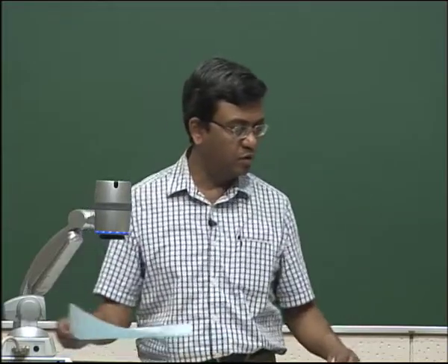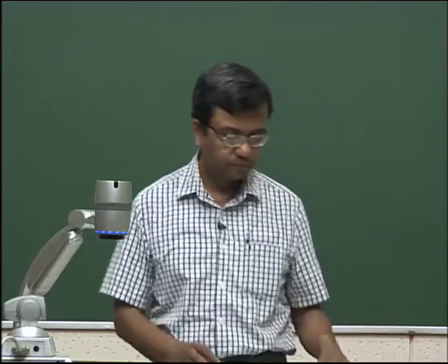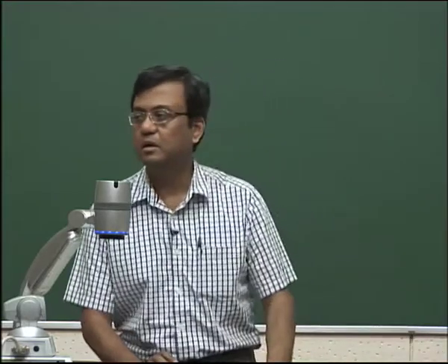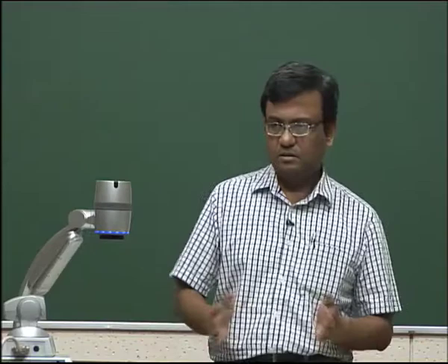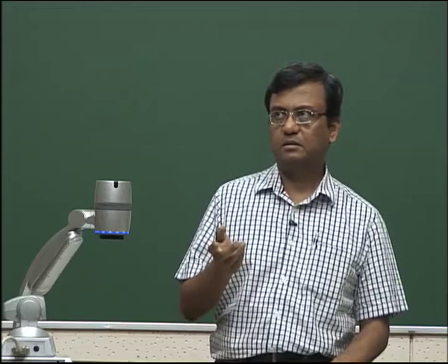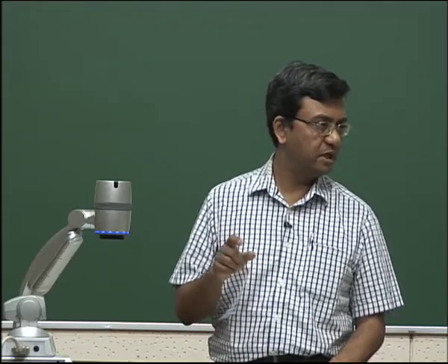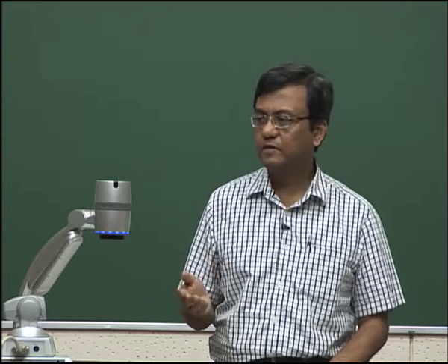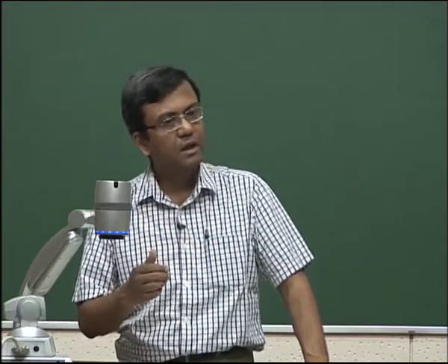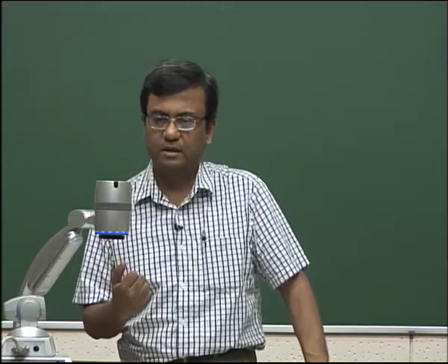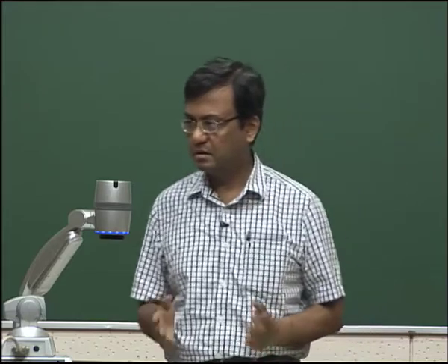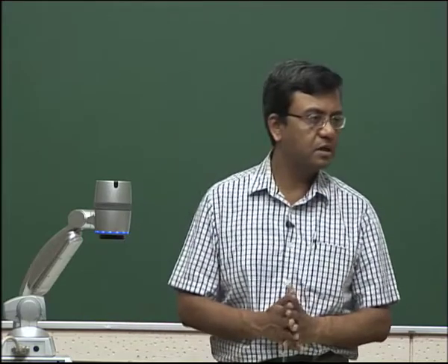So this is what we wanted to do with regard to droplet evaporation. Droplet evaporation is an easier problem which we wanted to work on. We saw that the equations are pretty simple. The only thing we needed was the mass conservation equation, to show that m dot is equal to constant, and also the Shvab-Zeldovich form of the energy equation, which involved some work, but we had done that work for a planar flame long time back when we were doing premixed flame analysis, isn't it? So we had done the Shvab-Zeldovich form previously for planar flames in 1D Cartesian coordinates.